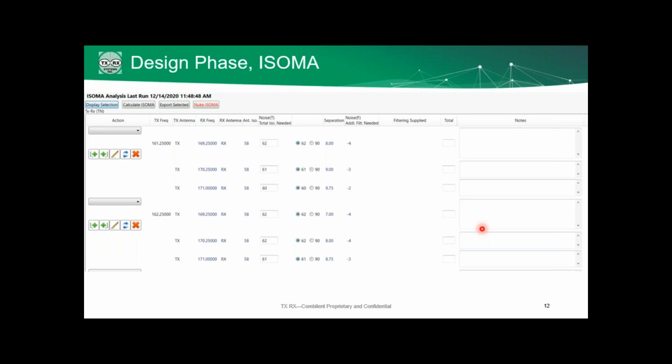So it's really important in a combining system to minimize the impact of a transmitter's noise on a receiver, and of course the impact on the receiver's sensitivity from a particular transmitter. So our filtering schemes are designed to suppress the transmit noise at the combiner and to provide filtering on the receive side to prevent any of that transmitter noise from getting to the receiver.